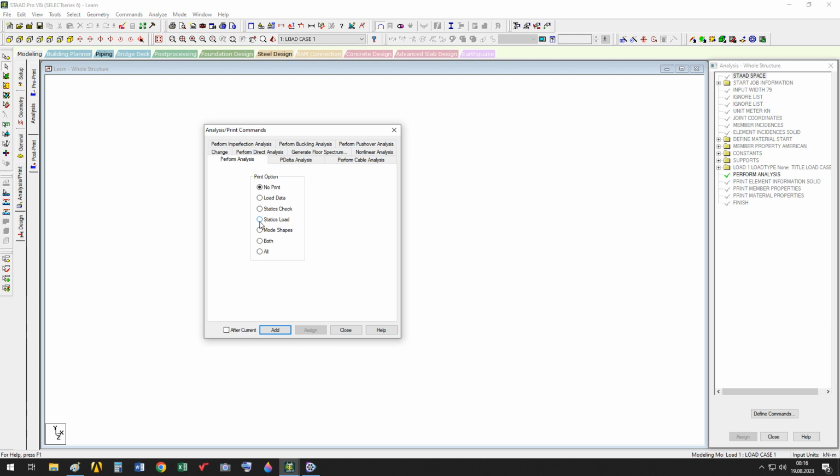Output file is not necessary, I think, because all results I obtain during the analysis are saved to the Staad file database, and by means of query or graphical user interface tools, I can obtain nodal displacements, reactions, support forces, support moments, several things.